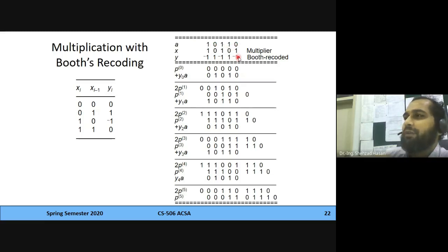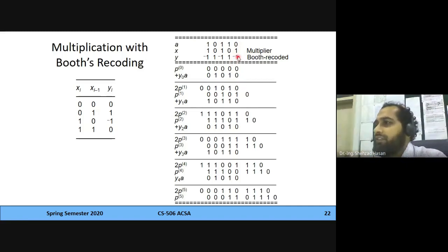So if it's minus 1, you are going to add 0, 1, 0, 1, 0. If it's 1, you're going to add 1, 0, 1, 1, 0. And again, take one extra bit to look for the sign, and then you're going to get the right answer. This is much simpler than the right shift algorithm, remember. Okay, so let's start. The first bit is minus 1, so we are having 0, 1, 0, 1, 0. We add these two, shift right.